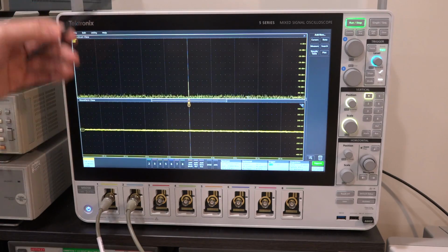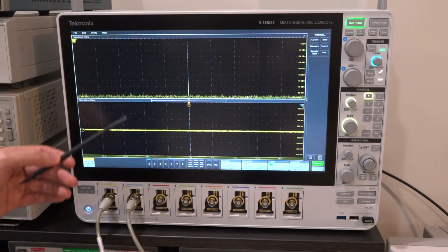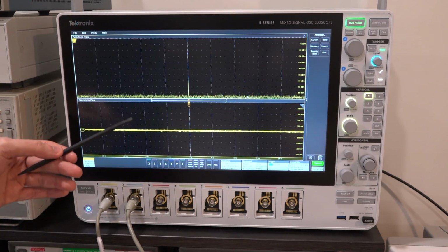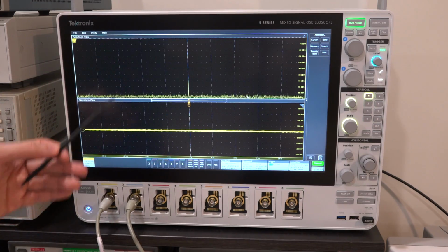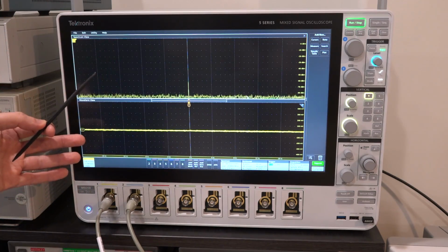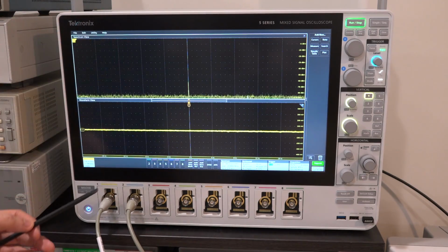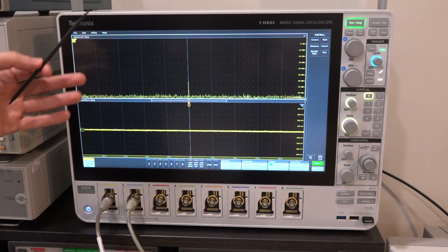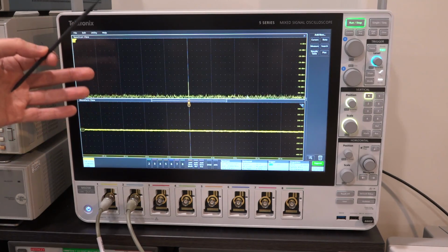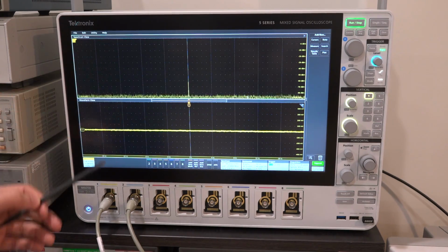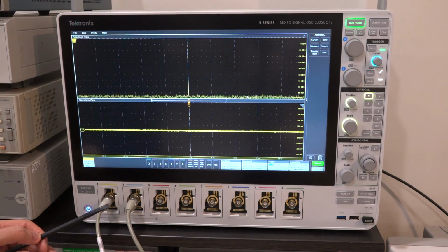The second reason is because the ADC in this system would have to capture the carrier and the phase noise simultaneously, whereas in a spectrum analyzer, the carrier can be removed through pre-selectors and other techniques in order to not have the dynamic range of the analog to digital converter occupied by the carrier. Then you don't have to resolve a tiny power away from the carrier while simultaneously trying to digitize the carrier at the same time. So a spectrum analyzer is inherently quite a bit more powerful for that reason.